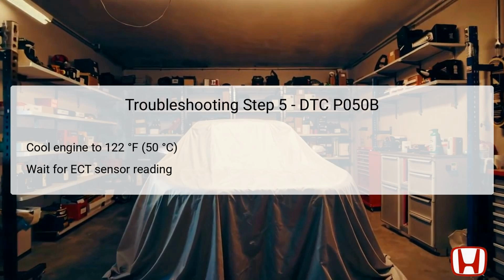This step is essential because improper coolant temperatures can result in inaccurate sensor readings, leading to erroneous performance metrics. Allowing the engine to cool down ensures that the diagnostics are conducted under proper temperature conditions, representing a typical cold start scenario. Once the ECT value is confirmed to be at the specified level, you can move on to clearing the DTCs and evaluating the system's performance under these controlled conditions.